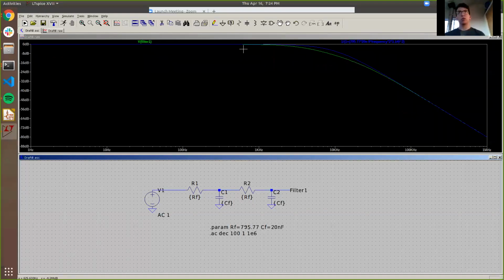And you might be wondering, okay, Corey, so our low pass filter cut off a bit lower than we expected. Isn't that fine if we're making a low pass filter? Yes, in this case, you could argue that, but you don't want your circuits doing things that you can't predict accurately. Because in this case, it might manifest itself as a lower cutoff frequency, but in other cases, you might not be able to predict what the coupling of two filters, or of multiple systems, may do to each other. So you want to avoid that as much as possible.